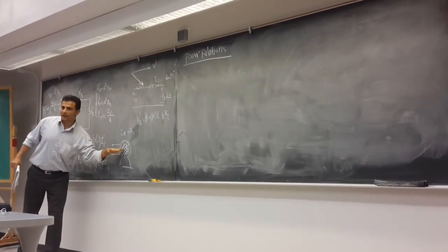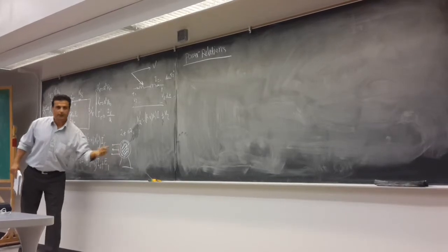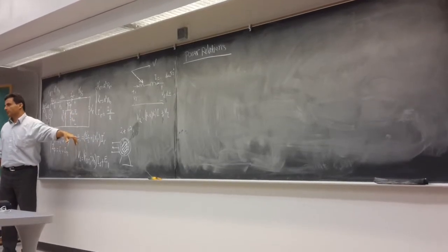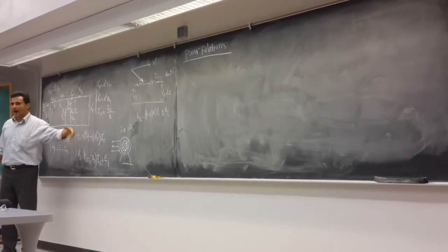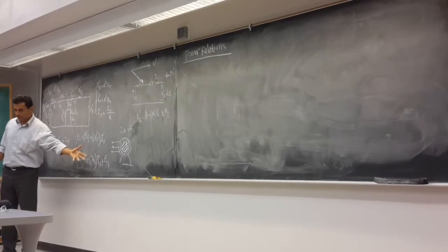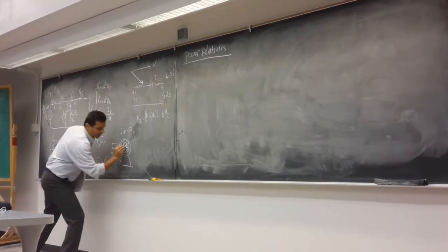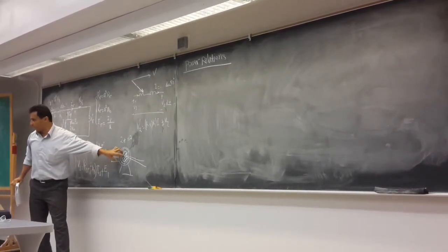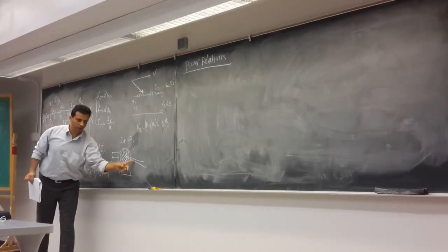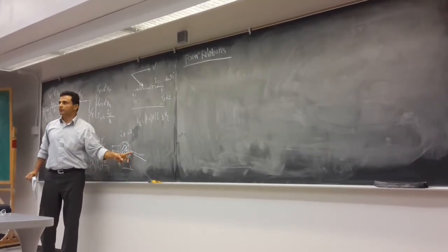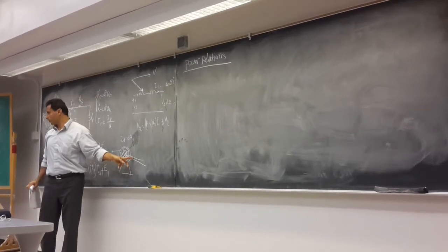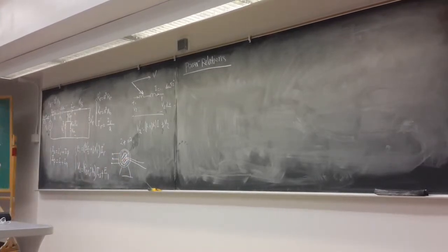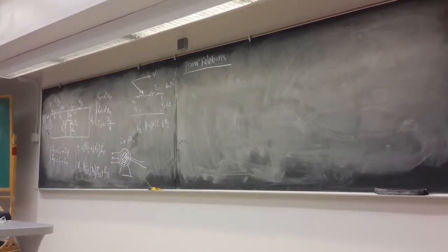The power is going through the air gap to the rotor, right? When we are in the rotor, again, what kind of loss do we have in the rotor? Resistive loss, right? Or copper loss. And what else? Nothing, right? So the power is going to come out from here. This is the shaft, right? So the power is going to come through the shaft out of the machine. But what kind of loss do we have here in the shaft? Friction loss, windage loss, right? That kind of loss. They call it rotational loss, because the windage and the friction are both because the machine is rotating.